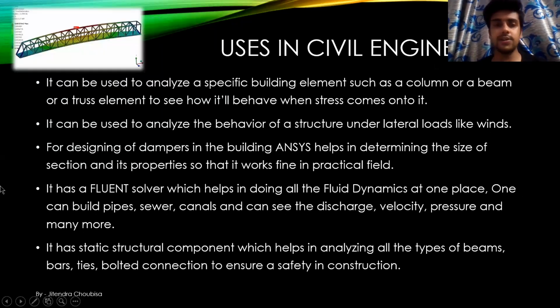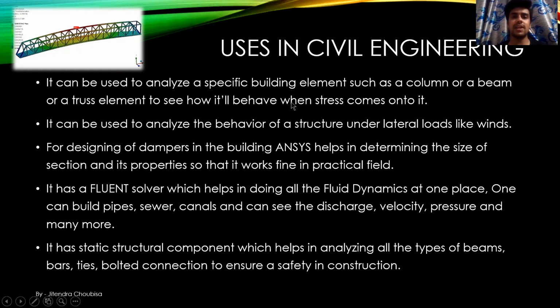Now, how can we use it in civil engineering? What is its use in civil engineering? That is what we are going to see. The first point is that it can be used to analyze a specific building element such as a column, beam, or truss element to see how it will behave when stress comes onto it. Let's say we have a column in our building, and it's the most critical column that we need to study. We can make that model in ANSYS, apply those loadings, moments, forces and pressure over it, and see how it is going to behave. We can see the stress distribution at each and every single level. So it is quite helpful in that case.